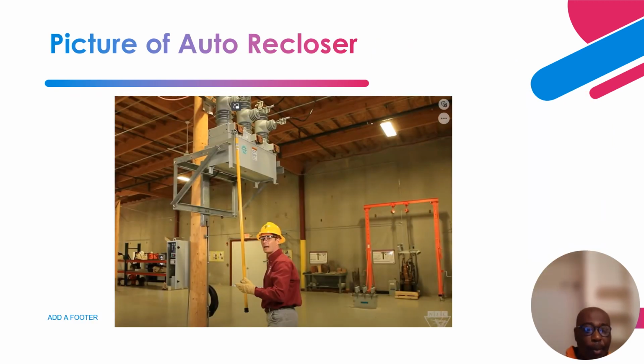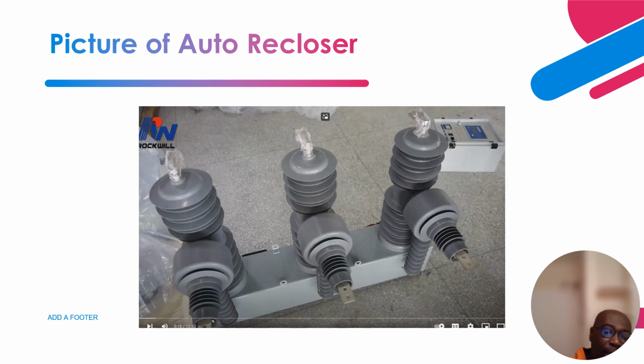Okay, so on top of the pole is the recloser. This is what you see. This is the recloser, so this is phase A, phase B, phase C. This is the controller. This is a mimic of an operator operating the recloser, open and close. That is manual operation of the breaker. Under normal circumstances, if the operator is not there, then it's this controller that takes care of this recloser.